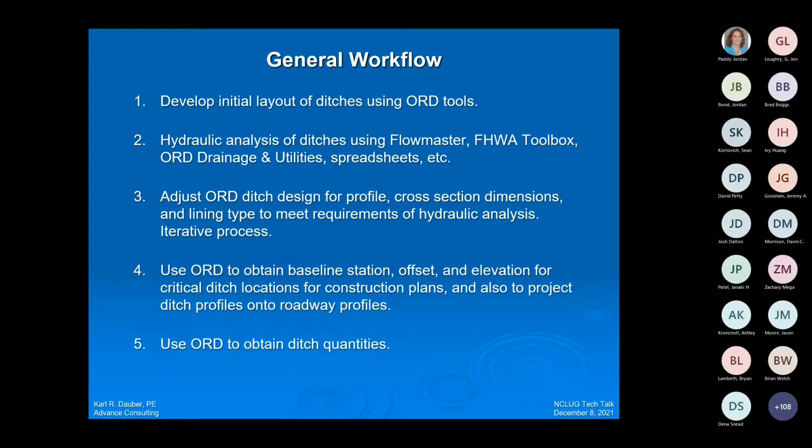So to briefly summarize the overall workflow, first, develop the initial layout of ditches using the ORD tools. And then you can do the hydraulic analysis once you have the profile set up of the ditches, using whatever procedures and methods that you like to use, whether it's Flowmaster, FHWA Toolbox, ORD, drainage and utilities, and of course, the spreadsheets that we all love. So whatever procedures you want to use for doing your hydraulic analysis, you can continue to do that.